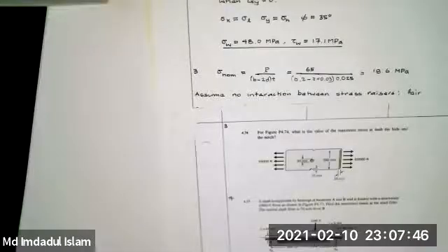I had thought in previous classes we'd said the threshold was once it was 4 diameters, you can ignore it. That was about 0.1%. But at 3 diameters or 3.3 diameters, the stress is pretty low. Is there a general rule that we should be using for this class for when we're allowed to ignore it? I'd say anything more than 3 diameters, don't worry about it. Okay, perfect.